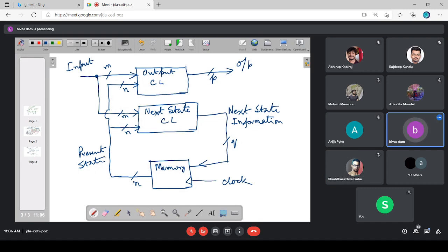Forget about the state information. Now consider the history information. Under which history information will the output be 1 when X is equal to 0? When the second bit is detected. So under that condition, if my current input X is equal to 0, my output Z should be 1. Otherwise, for other present histories, if X is equal to 0, the output will be 0.